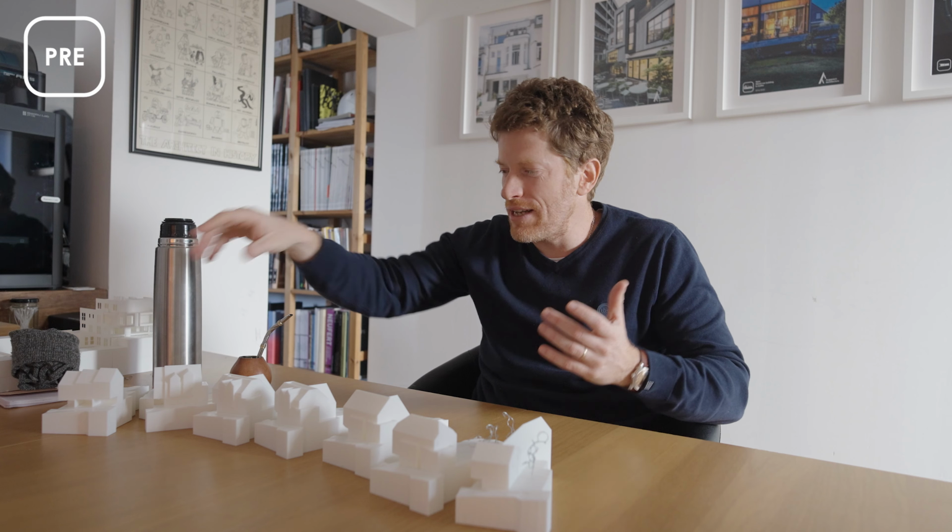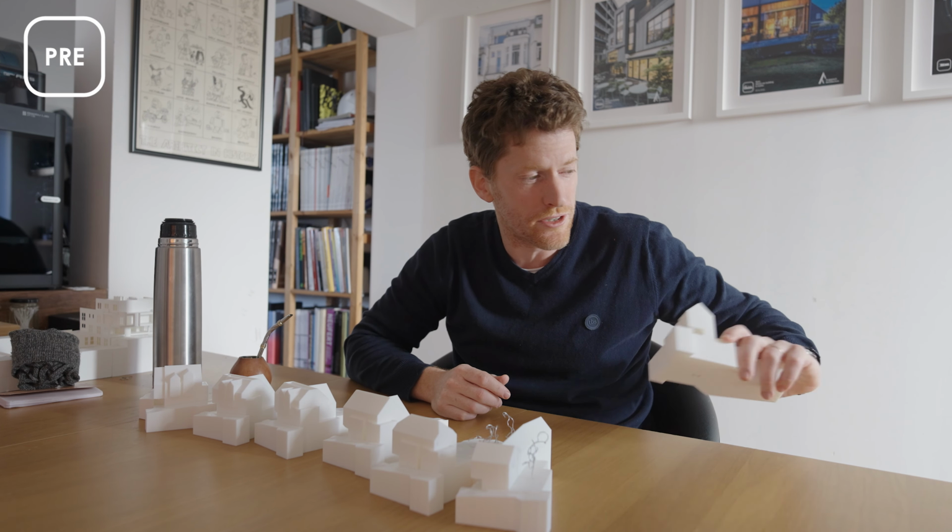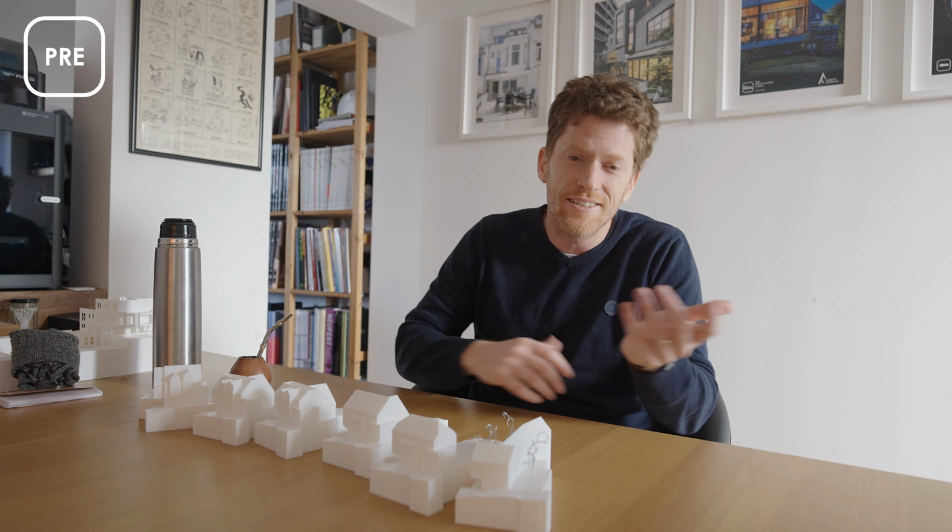And the worst part of this is that I'm proposing to the ground floor the opposite of a vibrant urban environment. I understand I'm only doing a residential project, but I'm certain I can offer something better than parking spaces on the ground floor. So we're definitely not going to do this option, because this would be the worst way to go. So all my other proposals accommodate, to an extent, my neighbor's windows. I'm creating a setback on the first 2 levels, and I'm creating a terrace on the final level.